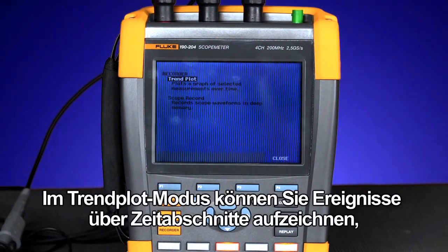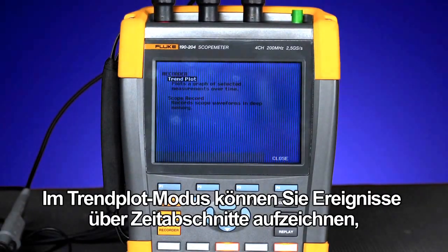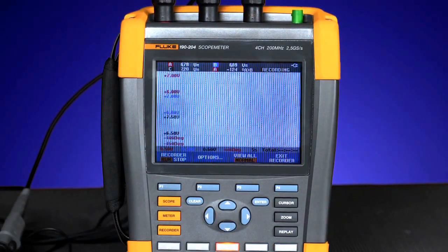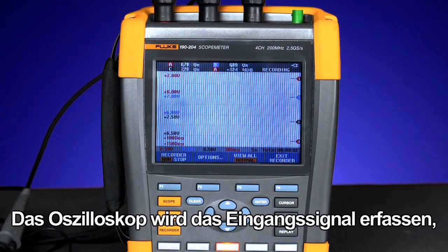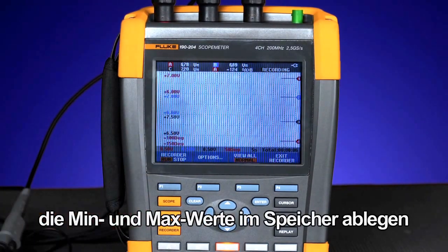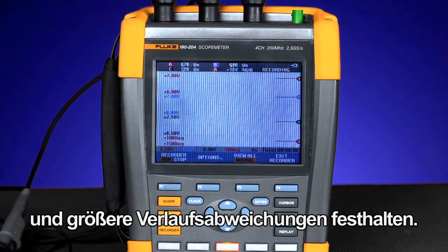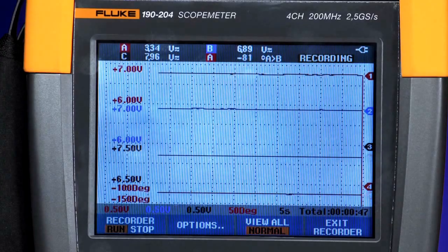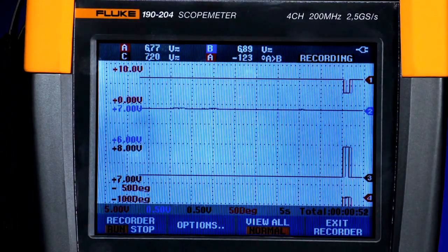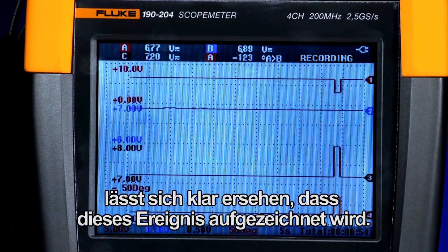In trend plot mode, you could capture or record events from as little as milliseconds up to 22 days. The oscilloscope will acquire the input signal, measure the values, and store the min-max values in memory, holding major event changes in record. When I invoke a change in the phase angle on the demonstration board, you can clearly see how the event is captured.